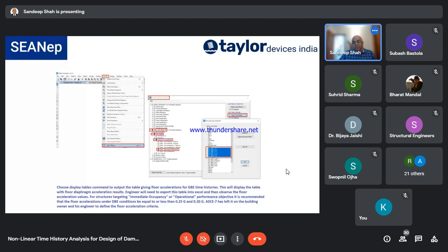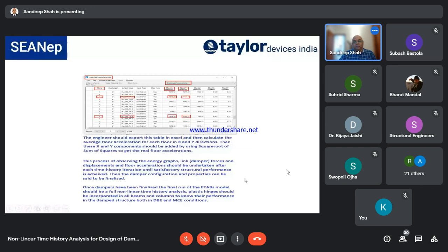So you choose these 6 load cases, DBE load cases, and you say okay. But when you say that, a table like this opens up, right? So it gives nothing but a story, different stories. It gives the load cases, and it starts giving you acceleration in X direction and Y direction. Z direction you need not consider, but X and Y is what you need to see over here. And I've just arbitrarily taken some points. This is DBE 5, and this is DBE 4, right?